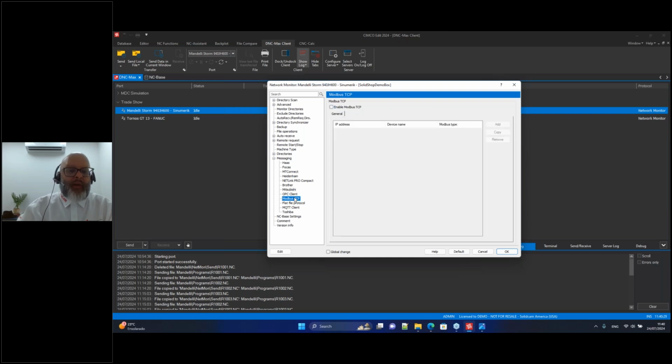Or Modbus for anything like, let's say you have an oven, a furnace, a robot, a conveyor on the machine, an automated device that is not a CNC machine. You could also have a little PLC there, and you could capture the information through Modbus protocol, for example, if your brake press is working or not, or if your furnace is working or not, and which temperature is inside the furnace, because you can do this. Okay.